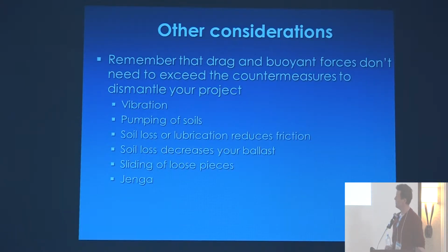Other considerations you have to think about: just because you did the calculation doesn't mean that everything's going to be fine. Wood can vibrate, especially during flood flows. You've seen this if you're canoeing down a river, you see sticks kind of vibrating in the flow. And logs can do this too. They start to pump out soils when they do that, and you get friction loss there. And wood can slide out. It can torque and start to dismantle your project. And that's why I have the Jenga reference up there. You pull out the wrong pieces, and you're going to have problems.